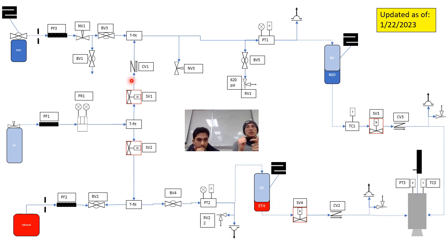And then we can go one of two ways. We either have some verification process that a human does that says, okay, I'm starting to see a little bit of a flame from the oxidizer flow, and right away give the go ahead on the test. It could be something where it's a dead man switch and it continues to go no matter what, unless they let go of the dead man switch, and then the test automatically shuts down. SV3, SV4 shut down, SV1, SV2 shut down.